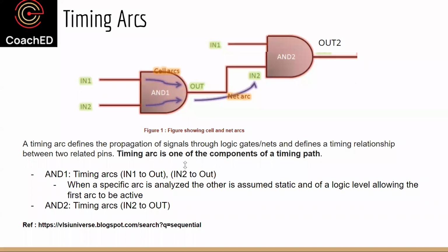So the divide and conquer method is more for pre-characterization. It's not for simulation's benefit. It's a benefit of pre-characterization. You basically are breaking down the design into small logic cells, and then you are just running simulation for those logic cells and pre-characterizing them. So that's the benefit of characterization. It's not the benefit of simulation. Simulation takes everything, and you have to run that. Any other questions? If not, then we will resume.